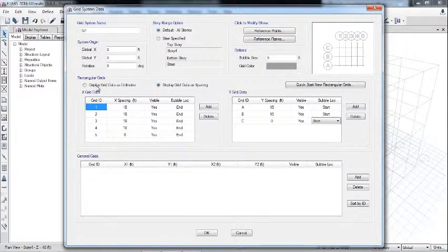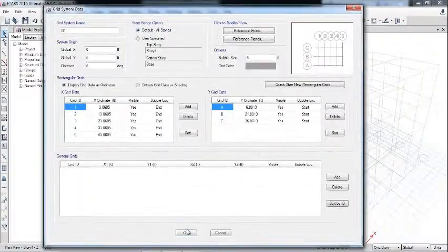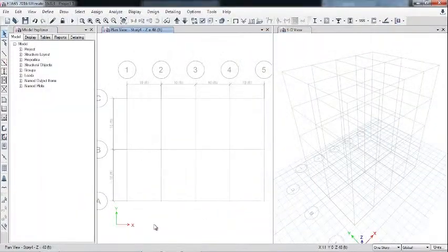You will also face one error. Here is a spacing 3.0605. Why am I saying this? Because when I click here, you can see on the right there are coordinates 3.06, that is not showing 0 0, meaning its X and Y is not at the 0 0.